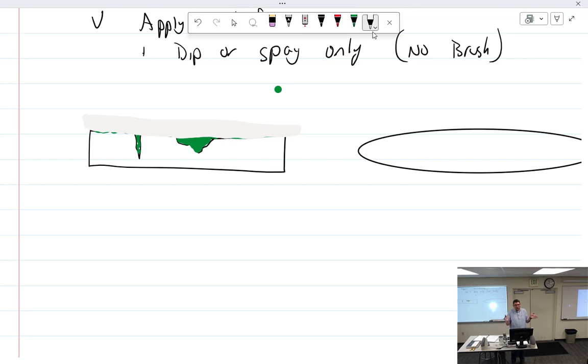You can get much wider indications, discontinuities to show up, because the emulsifier hasn't reached down to the bottom of it. Oh, so then if you have to do this on a test part, you have to simulate what cracks you're looking for? You can, and they make test panels that you can do this for. You just do the process.